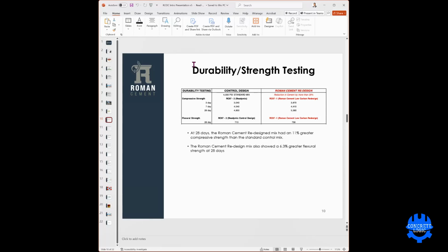Uh-huh. But this would be something John and I have talked about. We presented on it. This is something that would be fairly easy for a cement company to do, just to modify the particle size distribution in their cement by adding the stuff in at the cement plant. In fact, it could be dust from their crusher operation. It could be something they're producing. It's all about particle size and water demand, and balancing those two. John, we've talked about this, and I think there might be a company in South America doing something like that.